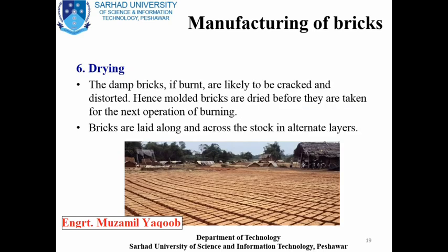After the molding process, the bricks contain some amount of moisture in them, so molded bricks are dried. The period of drying may vary from 3 to 10 days depending on the weather or the soil conditions.